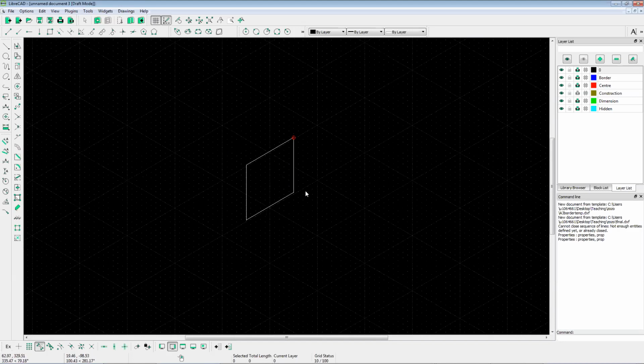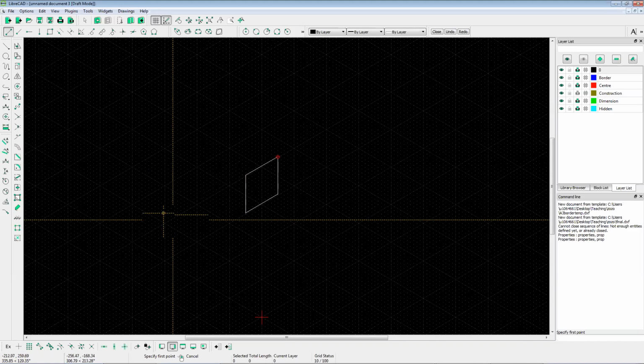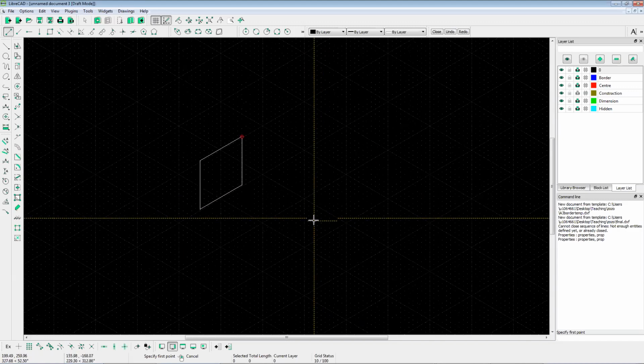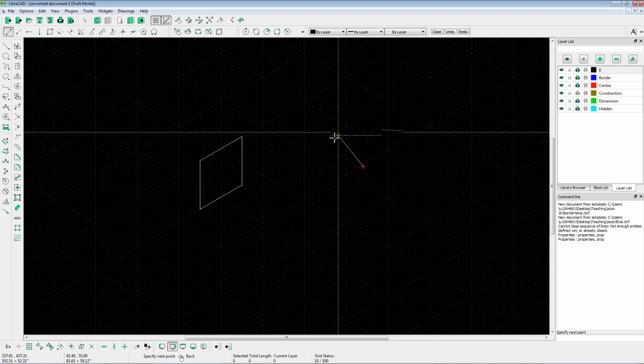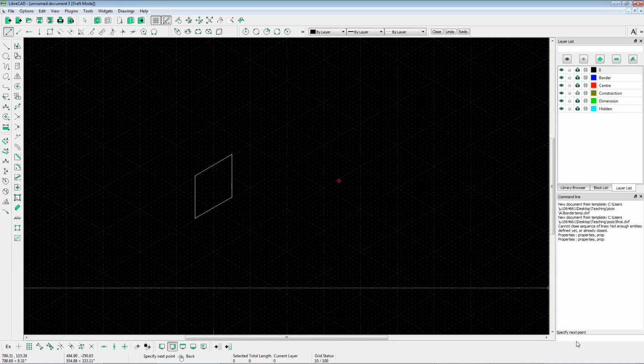And there is another way, we can use the command window here to draw lines. If you just grab 2 points lines, and let's say we just stop this for a while. If you just click anywhere here and then go to this command bar and type in @, which is for the lines, and then the length for the line is 100, and then define the angle as 30.